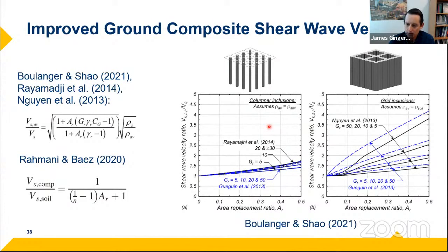The UCSD soil models are used here and there. My personal preference is typically PM4 sand and PM4 silt. Just has a lot of flexibility. It's very rigorously implemented in FLAC. It's got a lot of research and practice application behind it. So that's typically what we prefer to use.